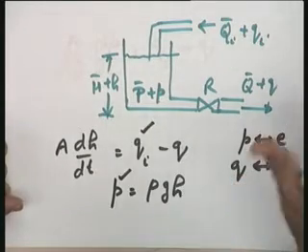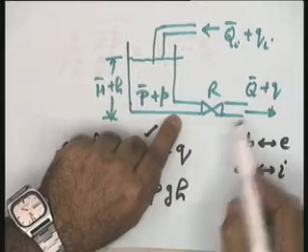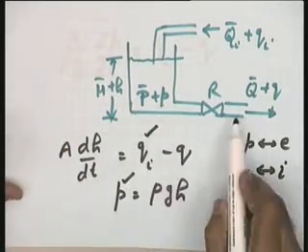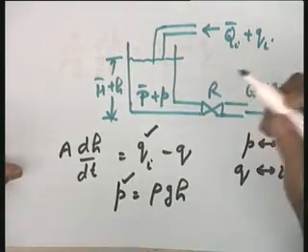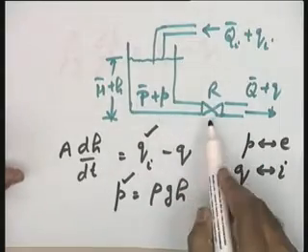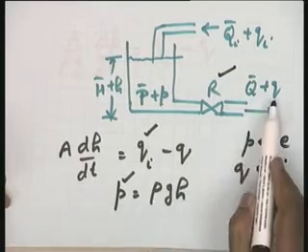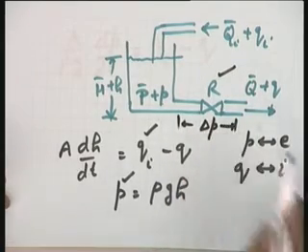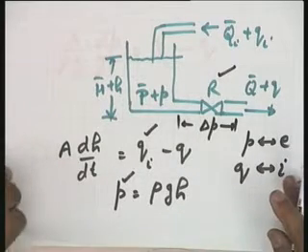The flow should be eliminated, and you know the equation. The equation, as you know, in this particular case is this. You consider this restriction. The flow in this particular restriction is given by the equation that flow is equal to pressure difference across the restriction divided by the resistance offered by the restriction. I assume that the manufacturer of the equipment has given you this parameter R. So, it means this Q is equal to pressure difference across this, let me call it del P, divided by the resistance R. Okay? Now, you have to help me for del P. What is del P?